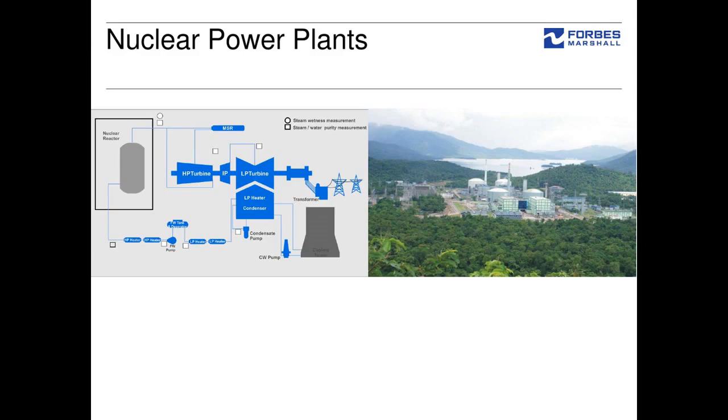Now, even in a nuclear power plant, the cycle which is implemented is a Rankine cycle. In nuclear reactors, there are different types. I will not go into more details of actual nuclear reactor parts and types. But generally in a nuclear reactor, there is a fluid like heavy water or light water which is heated using nuclear reaction, and this hot high pressure water is used to generate steam in heat exchangers.